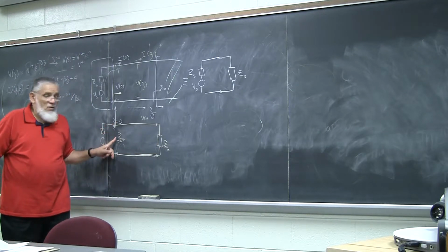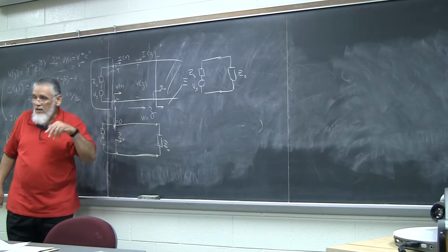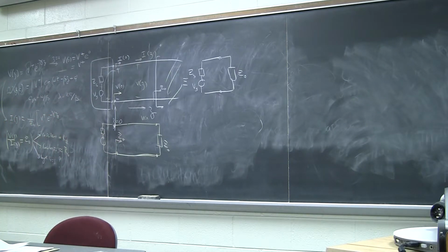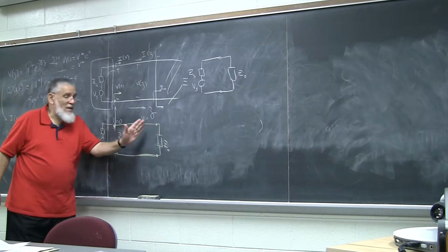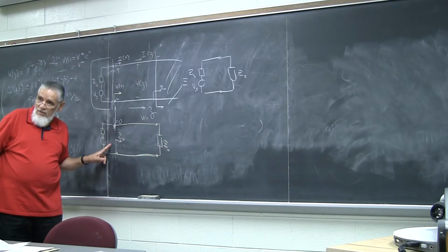So the input impedance of a line terminating in Z0 is Z0. That's a third definition for the characteristic impedance. It's the impedance that, if you were to terminate the line into it, would also be the input impedance of the line. It's a complicated definition, but it works as well. So any finite line terminating in Z0 will also give you Z0.